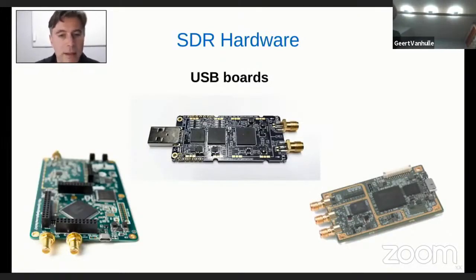So we see here typically it's a USB board. Depending on if it's an RX or TX combination or RX only, we have, for example, an RX and a TX input for the receive and the transmit. This is going into our board being digitized, turned back into complex samples, and this is the data stream that is being outputted via USB towards a general computing device like a laptop or another computer. So these are the typical USB boards that we would use here as software-defined radio in general.